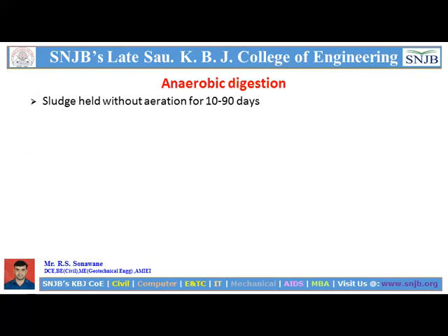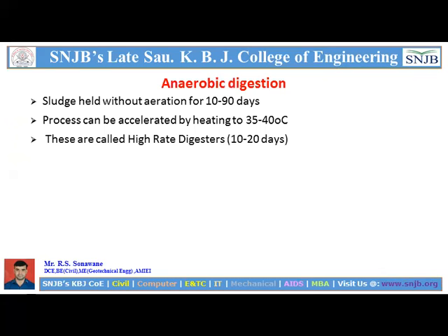Then anaerobic digestion. In anaerobic digestion, sludge is held without aeration for 10 to 90 days. The process can be accelerated by heating to 35 to 40 degrees Celsius. Then these are called high rate digesters. It may be lowered to 10 to 20 days.